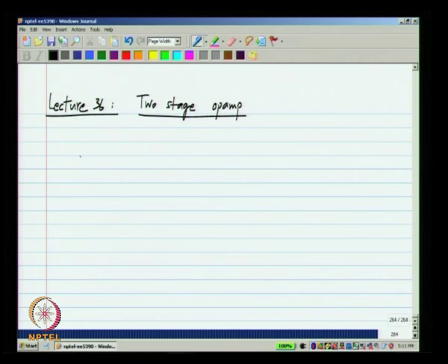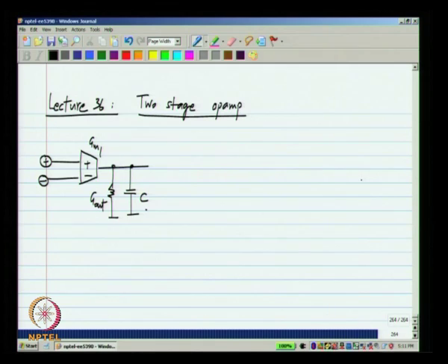When discussing the op-amp at the control source level, this was the basic op-amp. Now, we said that the problem is the output conductance of this transconductor. To obtain a better I to V conversion, the problem here is not all of the output current of the transconductor goes into the capacitor, some of it goes into this G out. To do better,